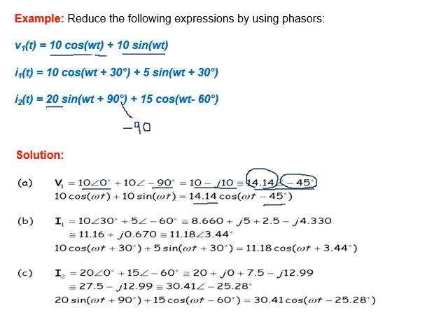So it will be, as you can see here, 20 with angle 0. This is cosine directly, so it's 15 with angle minus 60. Can I add them directly? No, we cannot, because they are polar. So we need to convert into Cartesian and real with real, imaginary with imaginary. After that, back to phasor, then from phasor to time domain.